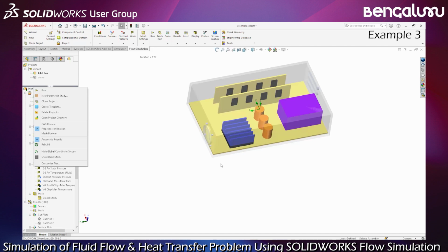And there is another tool which can deal with very dirty geometry of poor quality. It is named mesh Boolean, which doesn't work in 100% of cases. The mesh Boolean will try to mesh the complex part and work on the mesh to merge and do the Boolean operation.